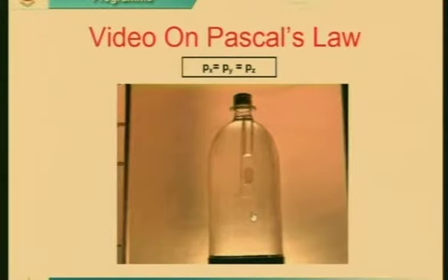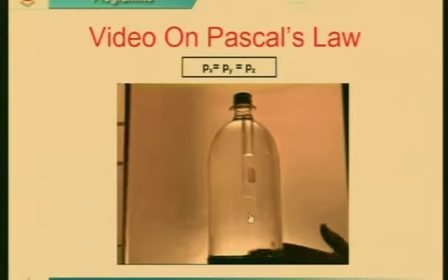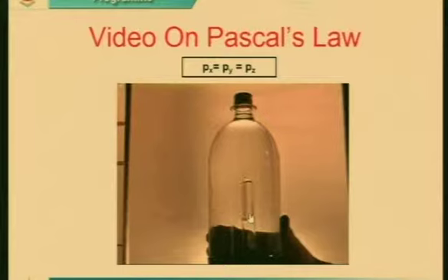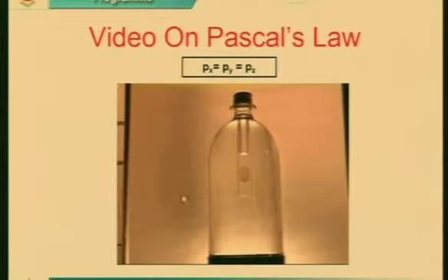Are you ready? Yes. Let us see. I am going to press like this, exactly as I showed. So, you can see that the element is moving down, correct. The moment I release, it goes back up again. It means the Pascal's law, or the fluid pressure, is transmitted equally in all directions. Repeat, the fluid pressure at a point is transmitted equally in all directions. It means at a point Px is equal to Py is equal to Pz.